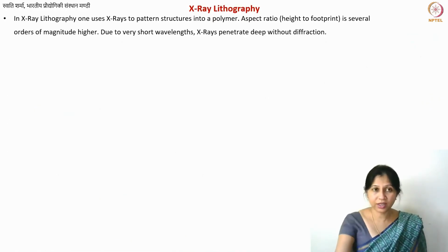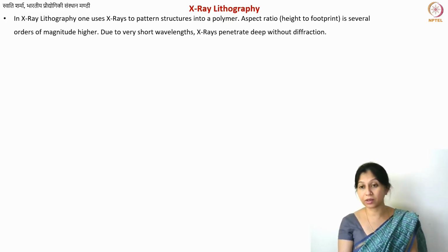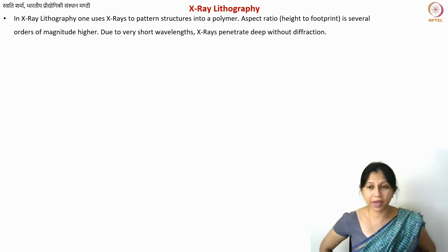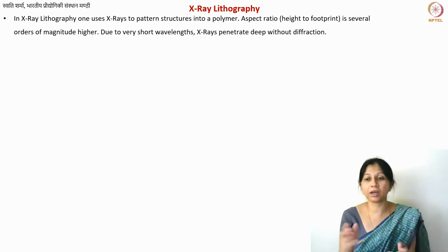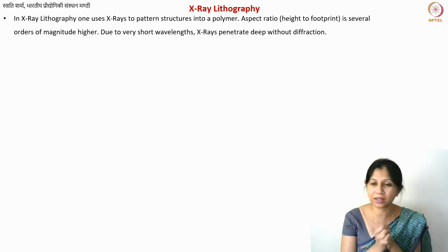Now the question is, are there also other techniques other than photolithography where you can get these structures which can be converted into carbon? So the answer is yes, because we have certain photoresists that can be converted into carbon. Now, with these resists you can also perform other types of lithographic operations.